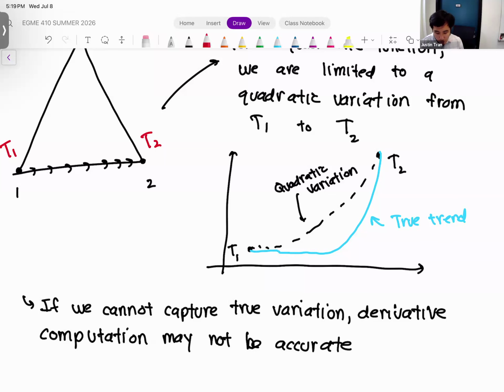But what we know, based on what we discussed last week, is that if we were to add more mesh density here, if we were to add more elements in between T1 and T2, then we add more control nodes on this plot. So in the red right there, let's say that we've increased the density of the elements there, so we've added more. And by refining the mesh in these regions, by adding more elements, we're more likely to capture these very sharp solution gradients.